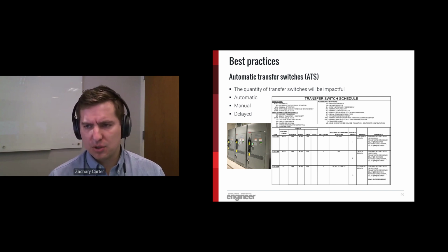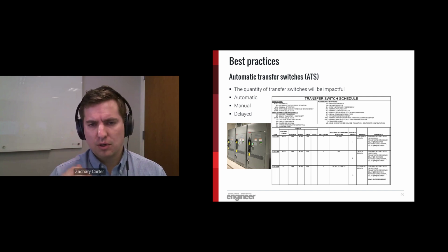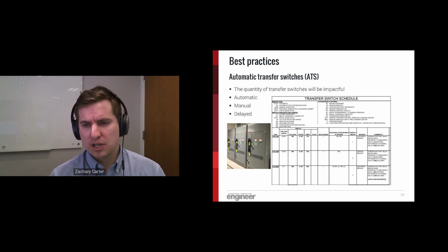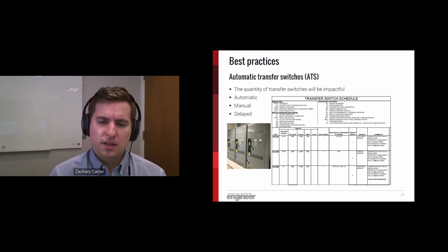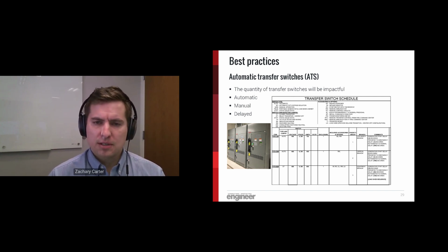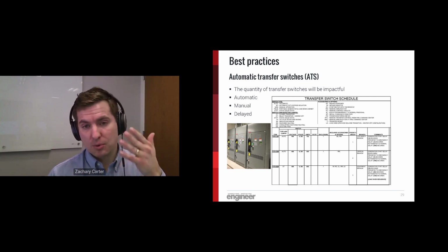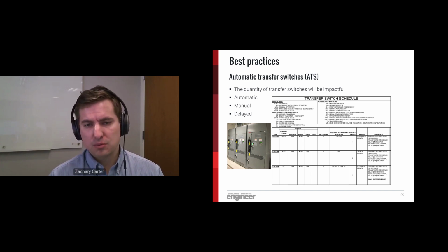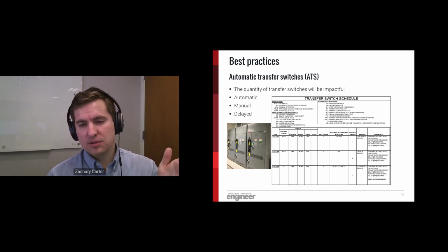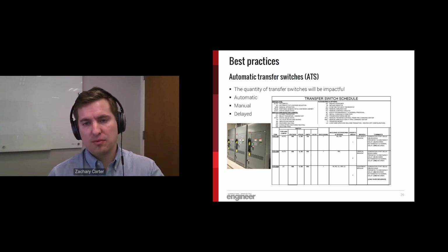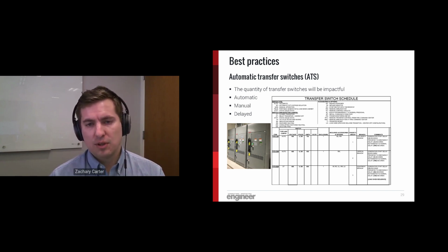The example in the transfer switch schedule I wanted to pull up here just shows a life safety or critical and equipment branch transfer switch. Again, this is that essential electrical system that I was describing earlier. Typically we will always have the priority column, the priorities 1, 2, and 3, because with the different layers of the essential electrical distribution system, the life safety loads need to come on first before the critical, and the critical before the equipment. So that's what the priority groupings are for.